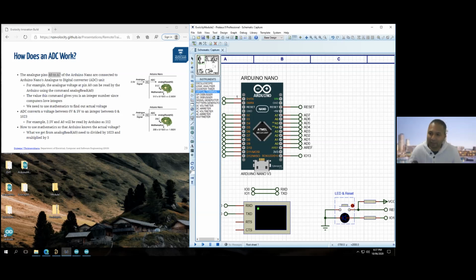Isn't it just letting all the energy flow from the battery? It's a voltage. You don't need to have energy flowing from the battery, you need to have a current flowing. Because the Arduino looks like a very big resistor, it doesn't allow much current from the battery to flow into the Arduino. So it just makes the voltage of the battery appear across your pin, which is a high voltage, 5 volts, which is a logic high. And when you release the push button, it creates 0 volts, which is a logic low. So if I just want to detect when a button is being pressed, I can just use the digital pins? Yeah, exactly.